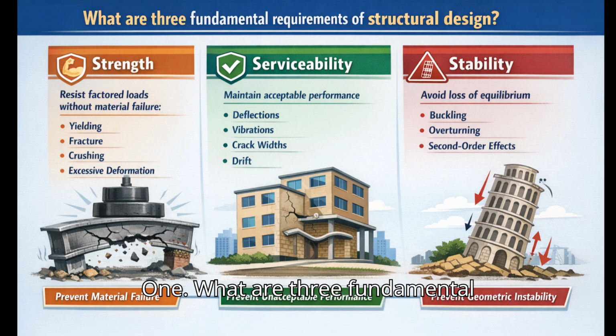1. What are three fundamental requirements of structural design? Strength, serviceability, and stability. 1. Strength ensures the structure can resist factored loads without reaching material limit states such as yielding, fracture, crushing, or excessive plastic deformation.